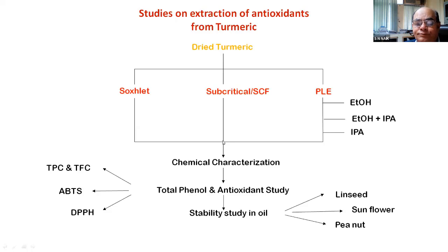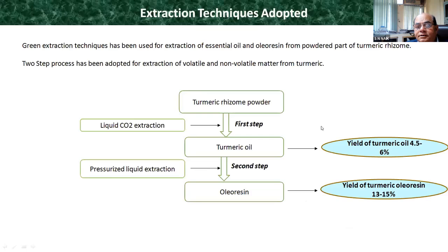to isolate the essential oil from the turmeric, and later the byproduct is taken by the solvent. After carbon dioxide, you pass a solvent like ethyl alcohol, isopropyl, and different solvents, and we optimize the curcumin isolation process and then characterize it and use it for antioxidant. So the first step, we take out the essential oil. Second stage, we use pressurized extraction.